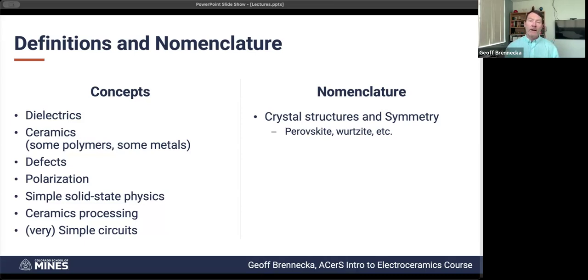intro portion. I am going to use the ceramics sort of convention rather than what you may hear from hardcore crystallographers or geologists or metallurgists or microscopists. So we're going to talk about crystal structures using their prototypes. So when I say perovskite, that's going to refer to the ABO3 sort of unit cell. That's based around the way that the ions are coordinated relative to one another.